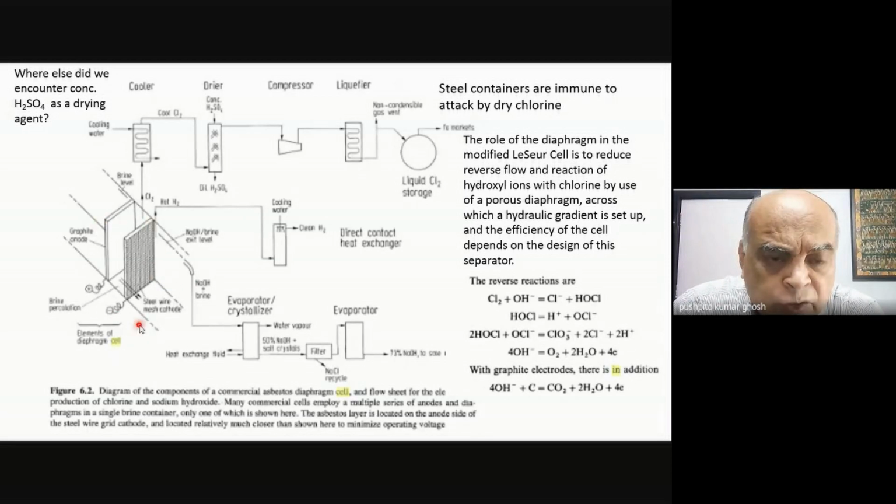But then, let me also tell you that there were problems. It's not as if all the chloride was becoming chlorine. It's not as if I put 30 grams of sodium chloride into my solution in a liter and all of it becomes chlorine. It doesn't happen. There will always be a certain amount which will remain unreacted. Second, because they wanted to really submerge the cathode with a flow from the anode, they had to increase the flow rate from the anode to the cathode, and that made it even more difficult to convert all of the chloride into chlorine. And so what is the penalty that one would pay because of that?